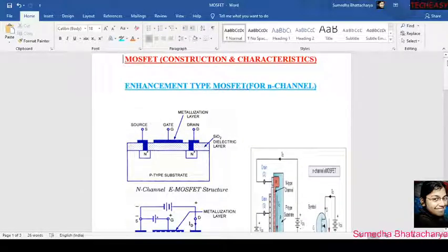So I will end today's lecture. I hope all of you can understand this video, because I have only told about N channel. You can also understand P channel, because the same thing will happen but vice versa, right? For P channel there will be an N channel substrate and there will be two P wells, but the work function will be somewhat different. But in this video I only discuss N channel enhancement type MOSFETs.